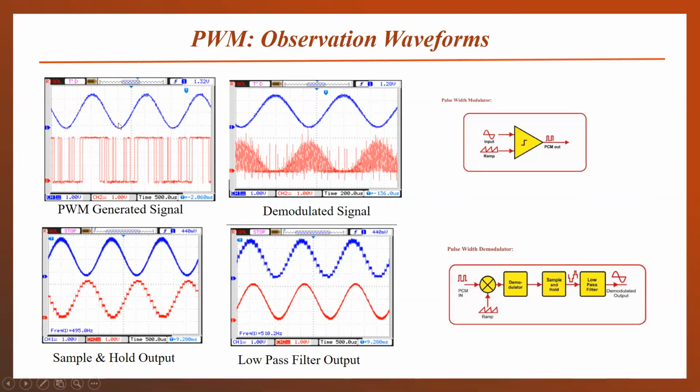Here the message signal is provided. The message signal is negative. The width of the pulses is very narrow. The amplitude of the message signal is increasing. The width of the pulses is increasing. Similarly, we can say the same pattern. As the message signal amplitude increases, the width of the pulse increases. And as the amplitude of the message signal decreases, the width becomes narrower.